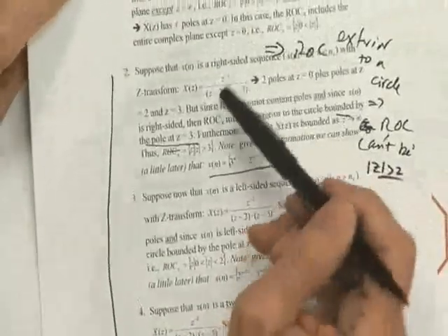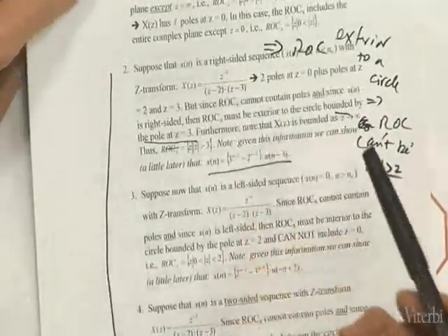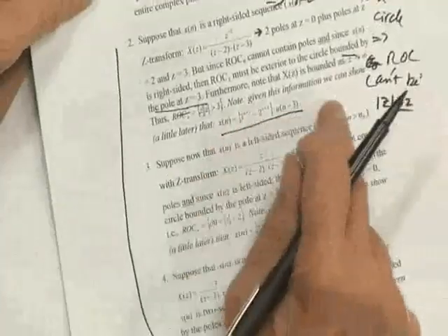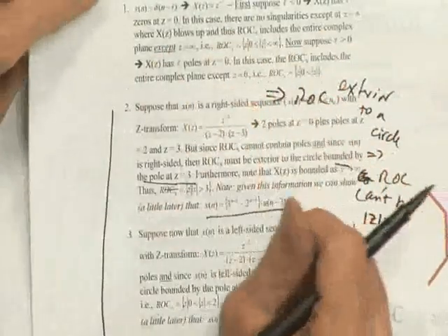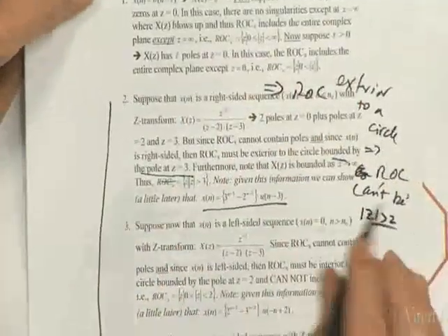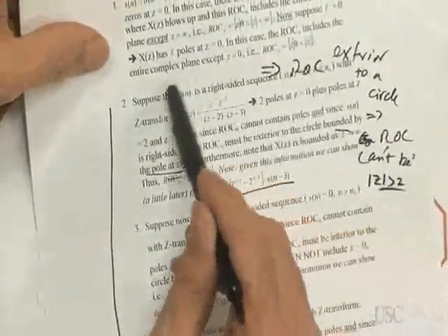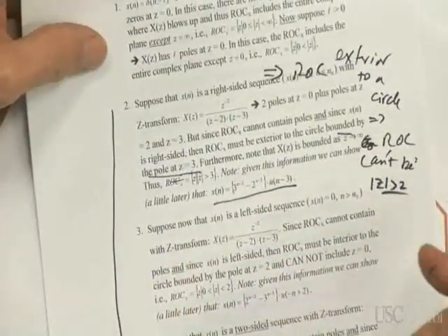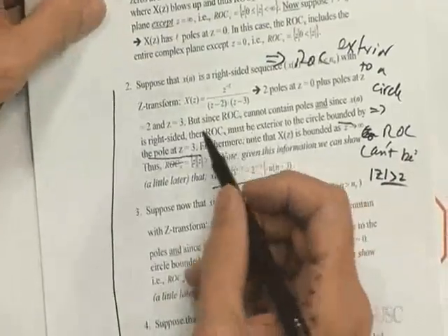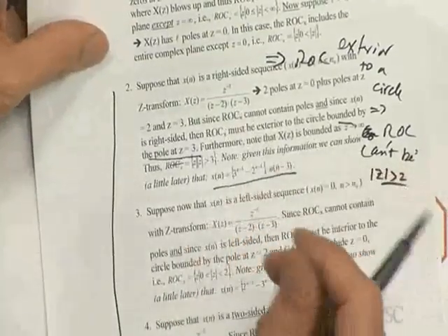Furthermore, you know what else I can tell you? I can tell you about the inverse z transform when you find it. Here it is, right here actually, and I'll go through the steps in deriving that in a few moments. I'll show you where that's done. But anyway, if I tell you it's right-sided, then you know something else. You know that the region of convergence is greater than 3.